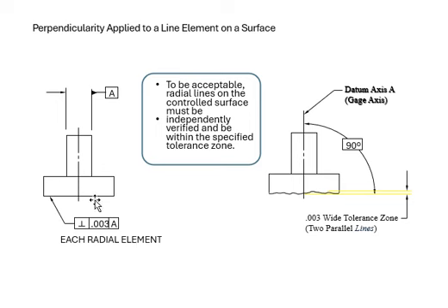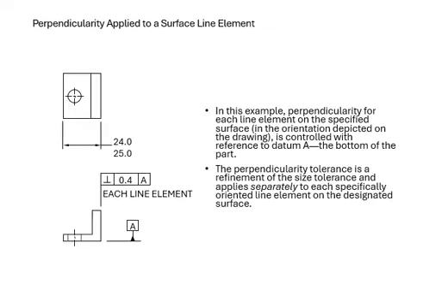It's just showing you your position and where your surface is, and from which reference plane we're measuring this angle. Now, as you know, we're measuring this axis and that surface, so your tolerance for the perpendicular lies right here. Yeah, and it's pretty wide. Of course, it's 0.003, but it's still acceptable.